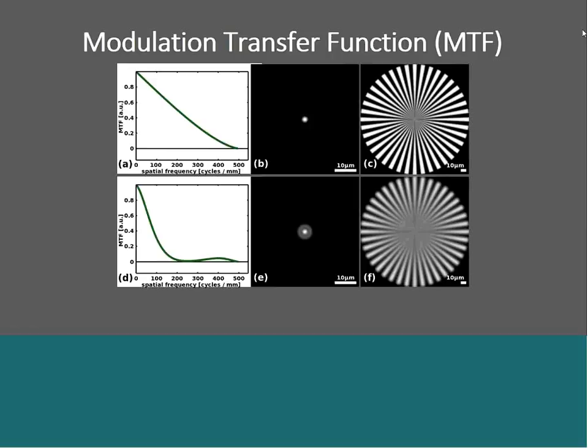At a spatial frequency of, say, 300, you can have a contrast of 40% or so, 38%, and you can see by the curve down below that you get almost nothing. So if the application is to detect a dot at a certain intensity, chances are you can use the lens on the bottom and you'll get acceptable performance.